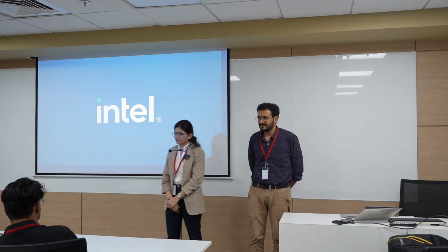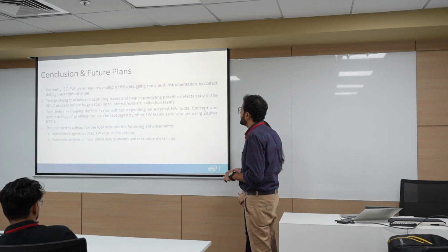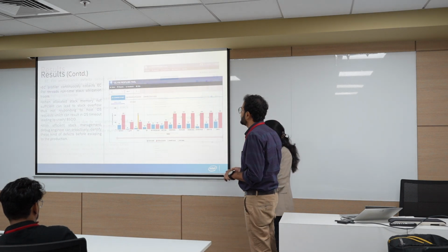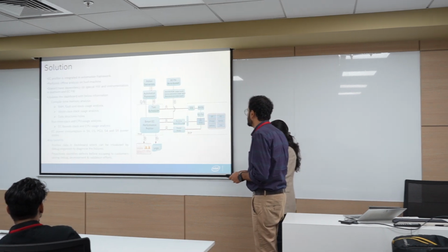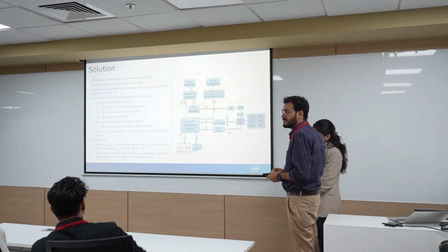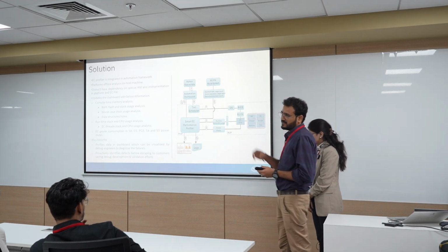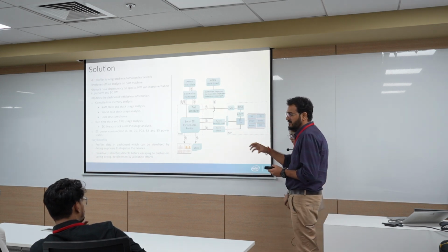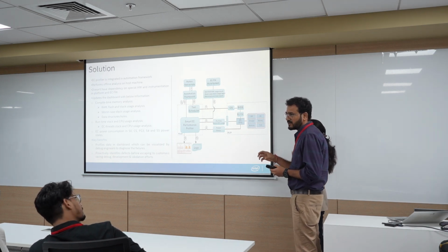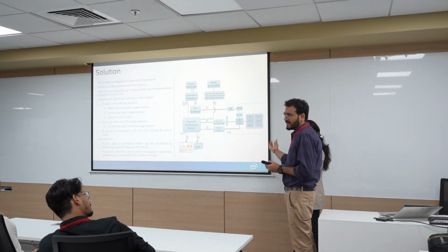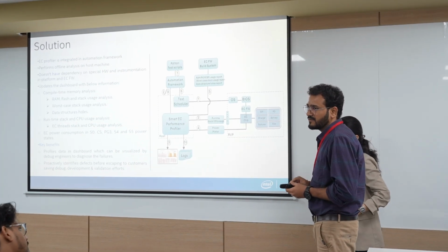Could you go back to that block diagram? Yeah, sure. Which one? This one. Okay, so this EC chip, that is where you flash this firmware? No, we have a SPI flash. Okay, a SPI device. So all the firmware will be flashed over that. EC is a microcontroller. What it will do is on boot up, it will try to get the image from that, and then it will load to the internal memory. So that's how the thing happens.